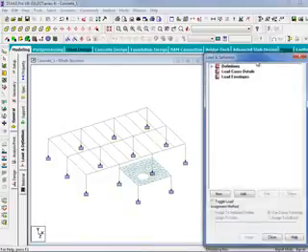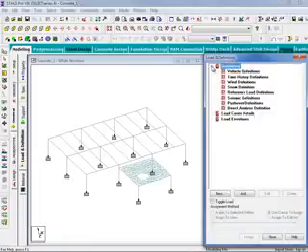In the Load and Definition dialog, we can see three groups are available, and we're going to be focusing on our load case details section. This is where we are going to define some basic load cases and also create some load items such as self-weight or member loads. In addition, STAAD.Pro does have the ability to generate some code forces for you, including wind load, snow load, and seismic load, and this can be done through the definition section.